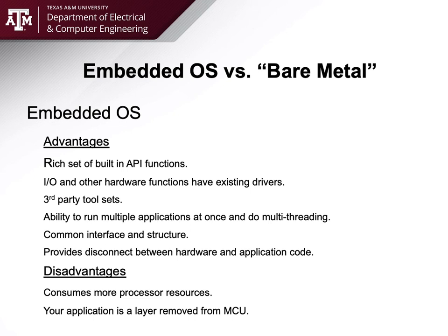I mean, just by default, you have an entire set of APIs and overhead now over your particular application. And so if you don't customize the kernel in the case of Linux correctly, you might end up with what we call bloatware. We have a bunch of drivers and a bunch of services that are firing that you don't need. You'd be firing NTP update, network time protocol update, and the thing's not even connected to the network. And just because you didn't disable it, this application's constantly looking for internet access that doesn't exist to update the system time. That consumes clock cycles. Kind of becomes annoying too. So that's something to pay attention to.